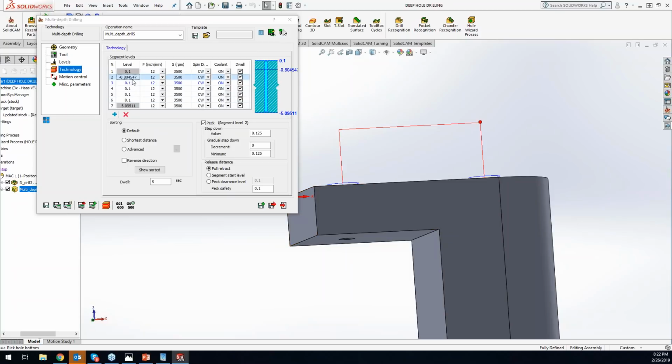Now, let's say that first half is 800 thou. I just want to go a little bit past, so let's just do 825 to round it off. Doing a feed rate of 12, and an RPM of, let's say, 5,000. And this one, we can do 5,000 as well.